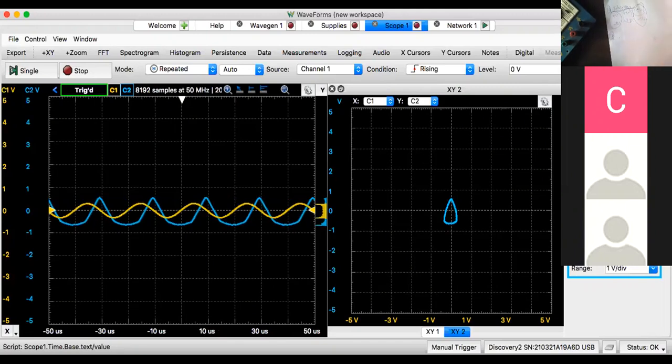The blue signal is supposed to go up to here, but now it only reaches that level. So it's a severe gain loss. So number 2 is a bandwidth problem. The amplifier only amplifies certain frequencies.